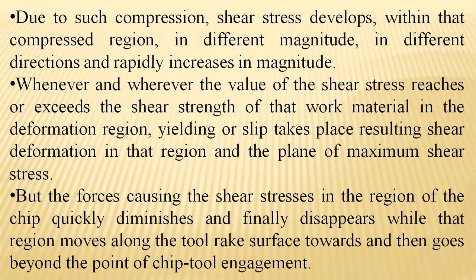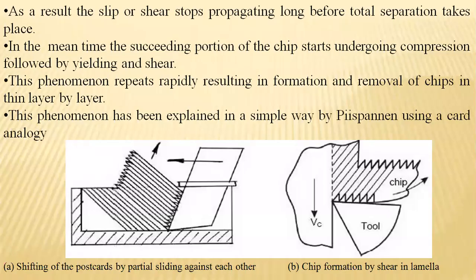And finally this disappears when the tool rake surface has moved on, and the chip-tool engagement will be a point that exists and separates the chip material from the parental material.